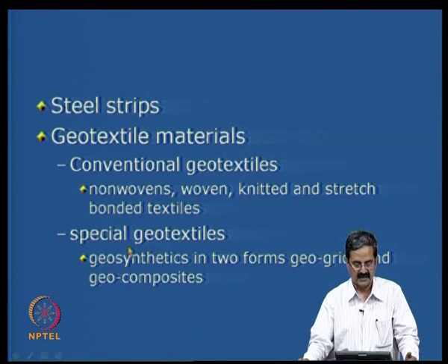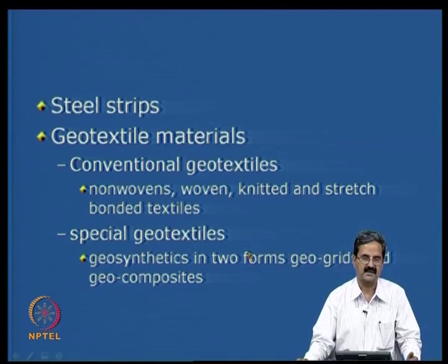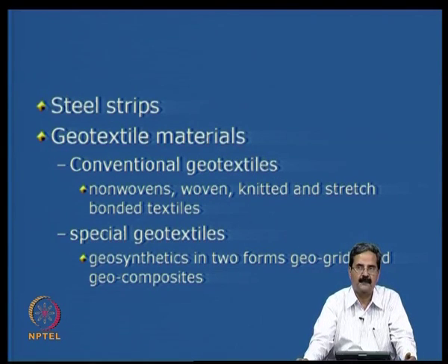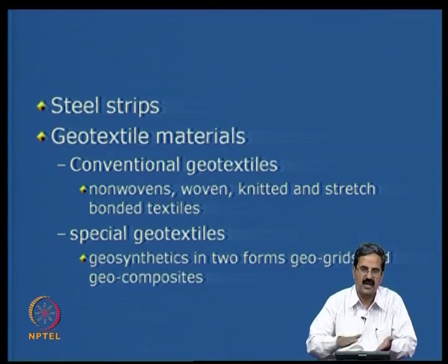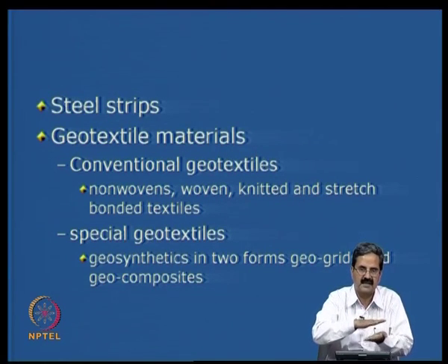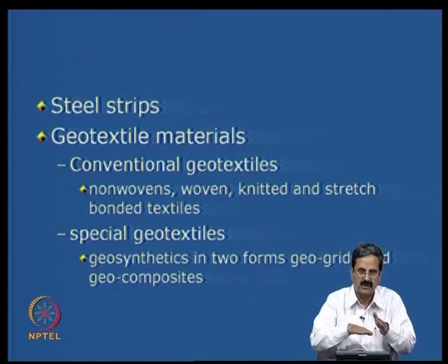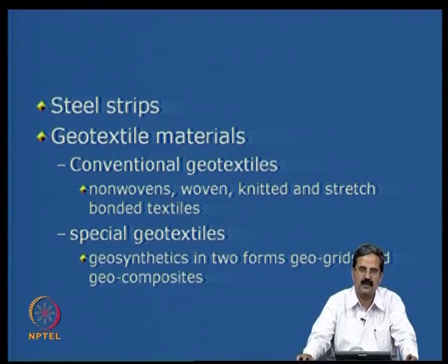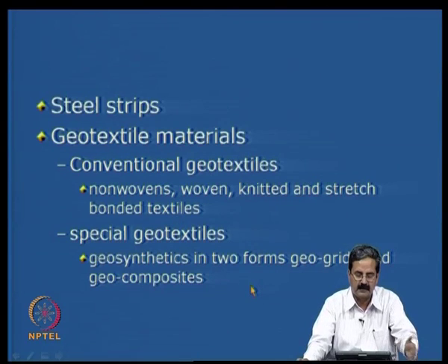Sometimes even special geotextiles, for example geocomposites, as I said, when the pore pressures are going to be higher, or if the clay is somewhat poor quality, we can use a geocomposite in which you have a reinforcement as well as a drainage material attached to it. So, the reinforcement is good enough to take care of the lateral pressures, and the drainage action of the geocomposite helps in draining the backfill.